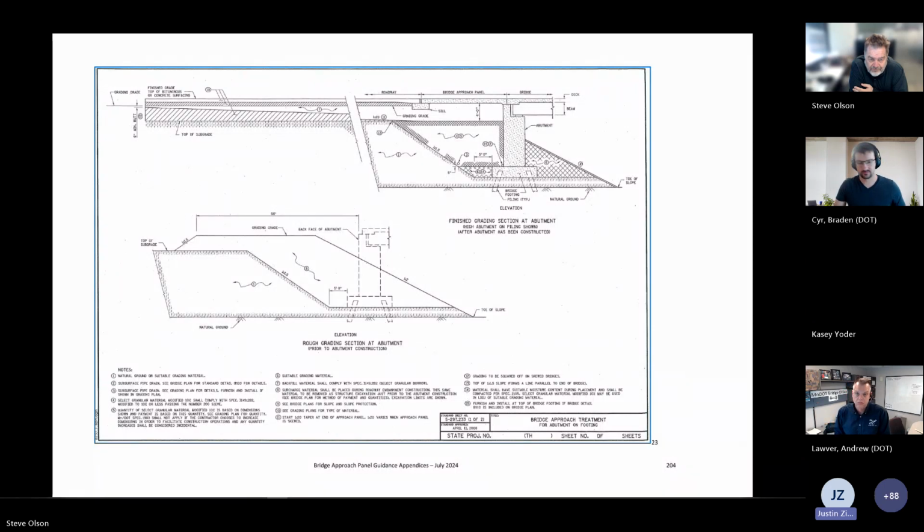I was looking into what to recommend to the city, and actually found this MnDOT document titled "Synthesis of Bridge Approach Panels Best Practice" from 2013. Right in the executive summary, they were saying that the E8 joint hasn't performed well, often failing within 1 year of service, which is kind of our experience. So it could be some susceptibility to installation procedures, but I'm curious if there's something being developed that's a little more durable.